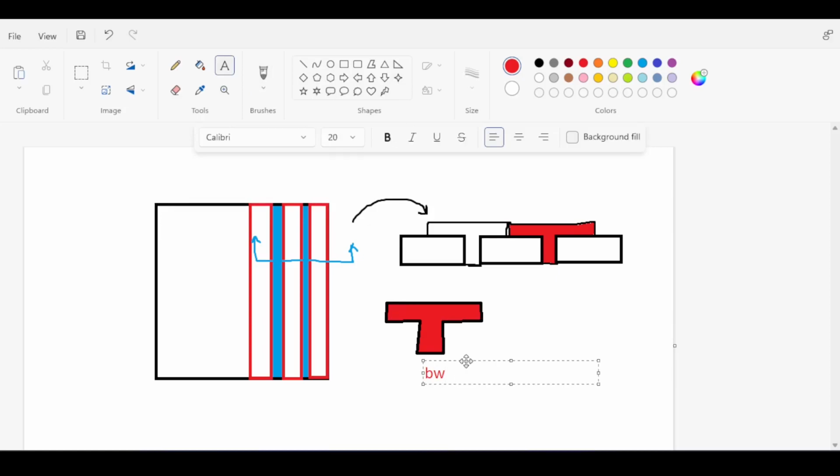Now, the lower width is the width of the web, and this is usually the spacing between the blocks, and sometimes it's taken between 100 millimeters and 150 millimeters. I'll take it as 120 millimeters. And what about the upper flange width, B flange?